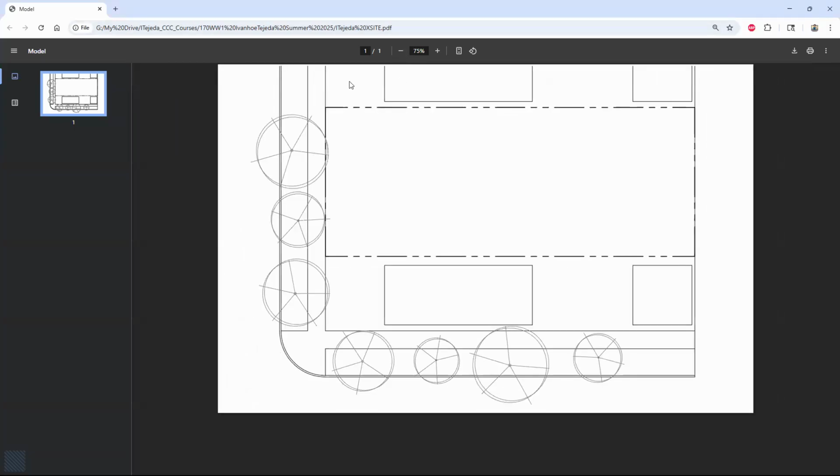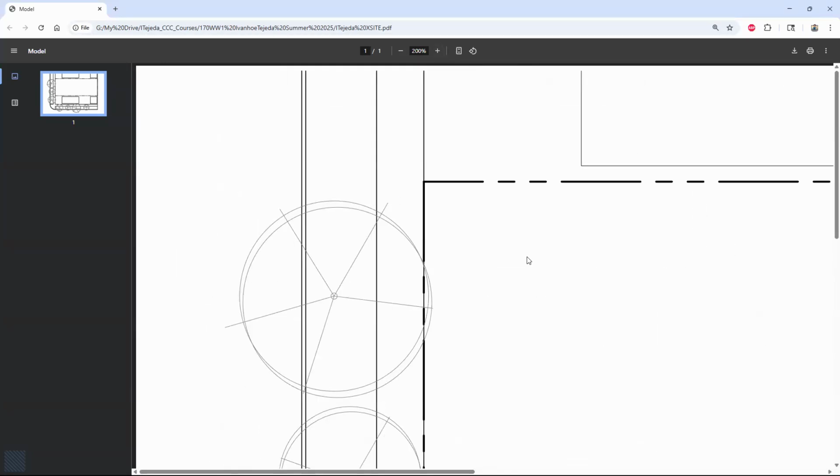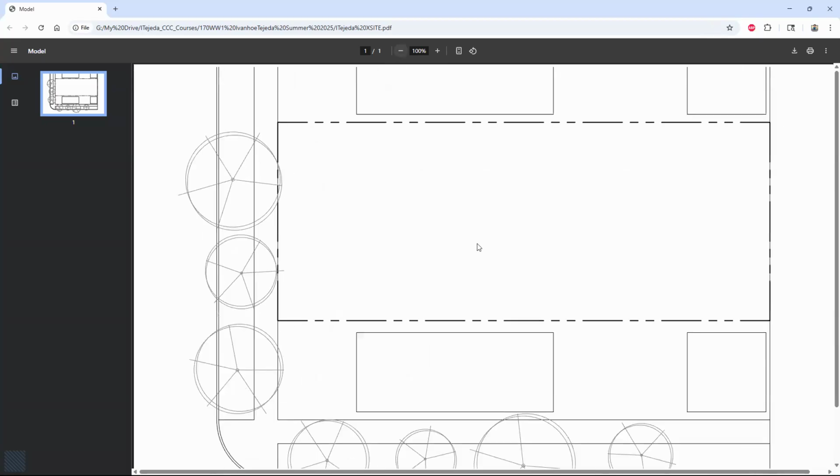You can see it fit on that sheet, 11 by 17, at the scale that I requested and to the window that I had requested. And if I zoom in closer, really get in there, I can see the difference in the line weights and also how I set the color green to halftone. So I like that setting, but again, any way you would like to set it, just remember the hierarchy here, and that is that the property line has to be the boldest line on this drawing file. All right, and that's all done.